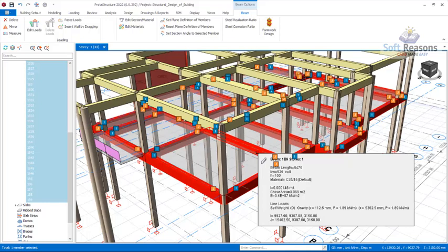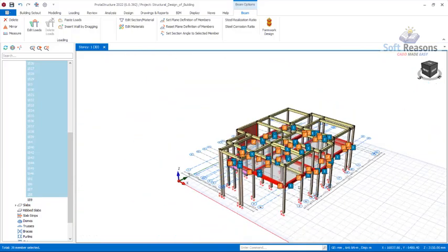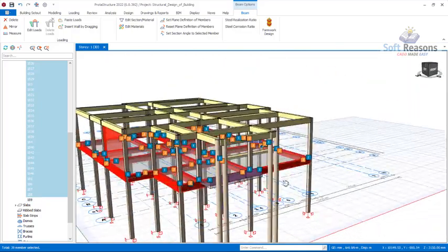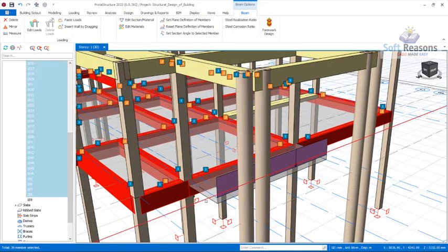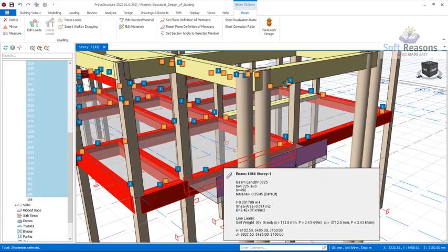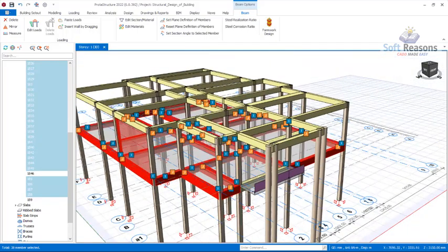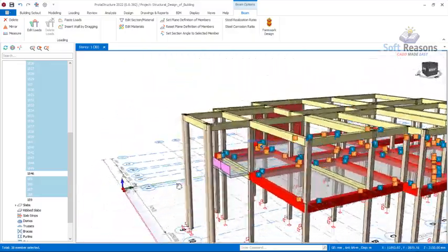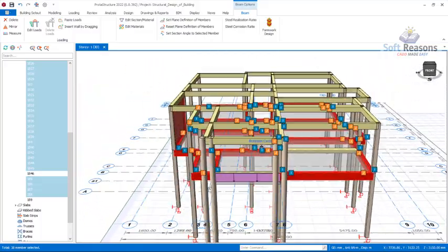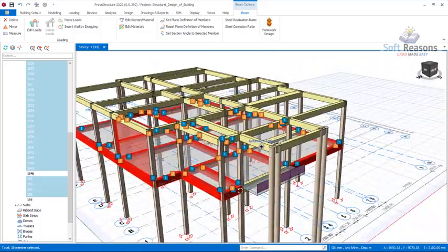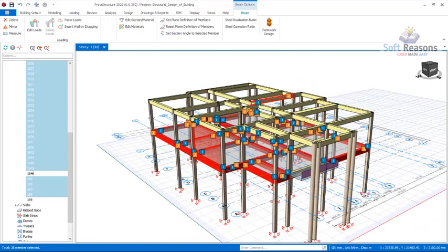But if you want to get rid of a beam being selected, hold the Control key and select the beam. Right, so that is how you get rid of the beams that wouldn't carry a wall load. Okay, so this beam also is not carrying any wall load, it is just supporting this cantilever slab, so you get rid of that beam. Okay, so I'm just doing this to show you how to deselect beams that are not carrying wall load successfully. So we now have to paste. So you right click or you click on paste load in these provisions.